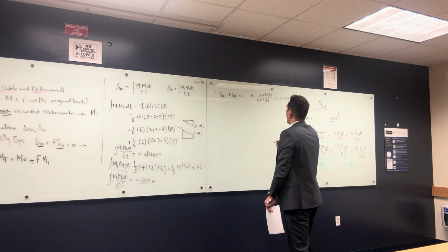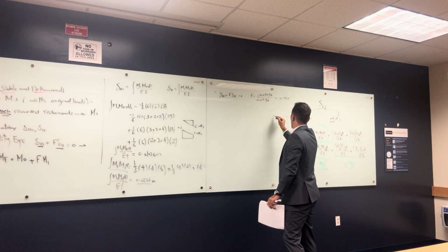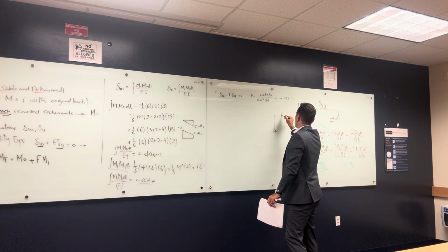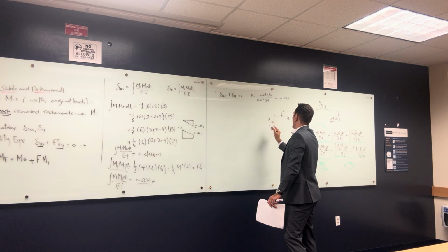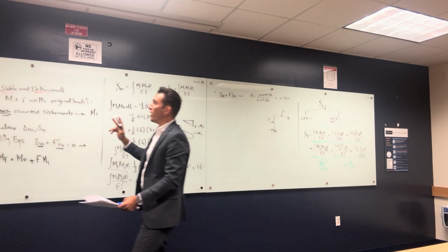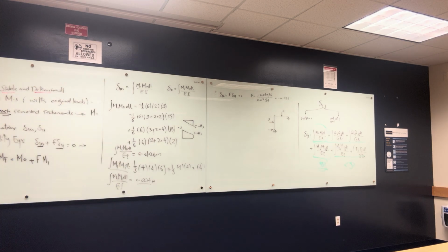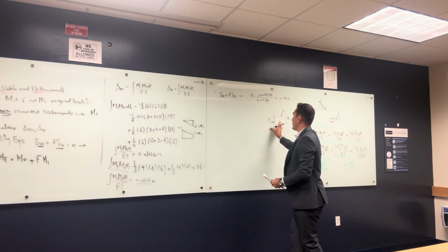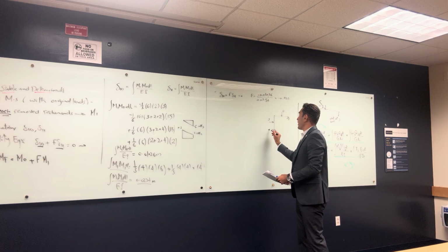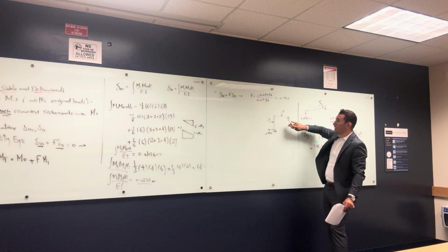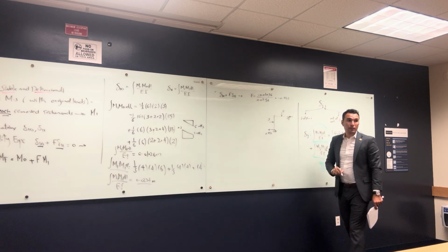All right, so right now I find the reactions. This is my beam. I have a hinge here and a hinge here, and I have a load 6 and 3. And I know what is the value of the reaction here. By the way, I assume the unit load going this way, right? It's 1. But when I got the final reaction, it's a negative. That means that my assumption is not right. It should be that way, and it should be 0.452, and that makes sense. Because when you push that way, they have to be the other way.